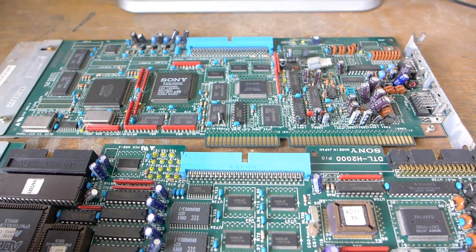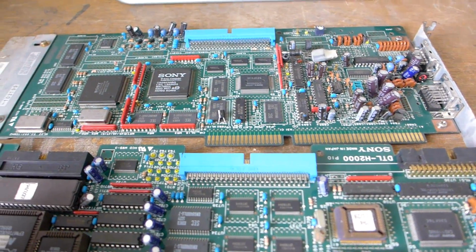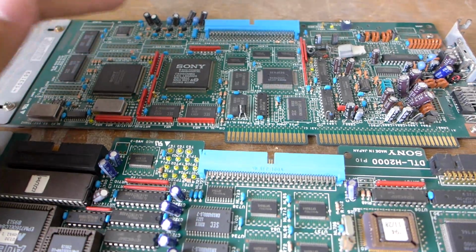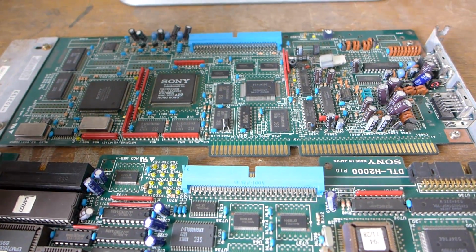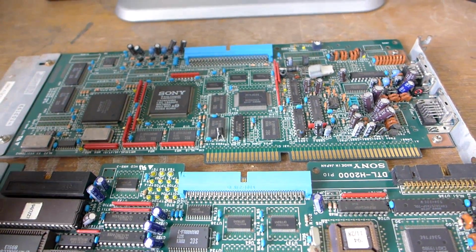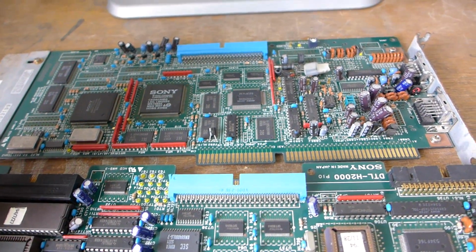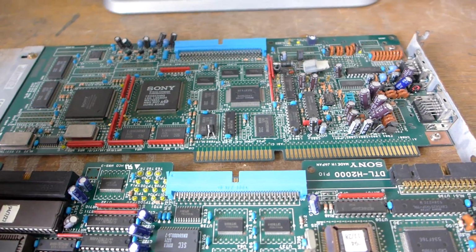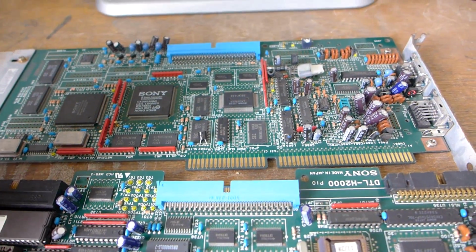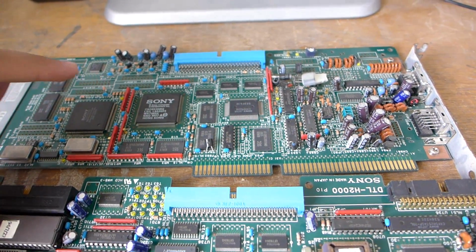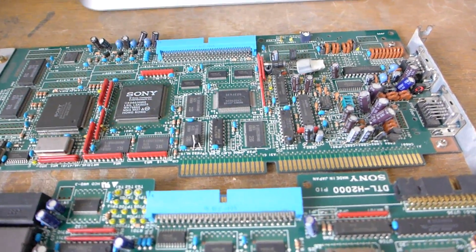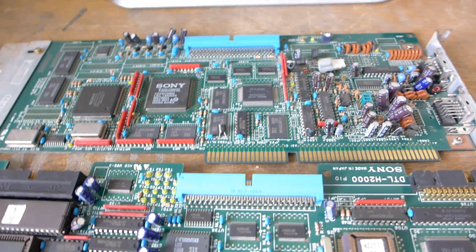And also there are two versions of the CPU board. The earliest one has a ceramic heatsink on the CPU, which resembles the very early Japanese launch units, which also had a ceramic heatsink on the CPU. The difference with that, as opposed to this revision of the DTL-H2000, is that the one with the ceramic heatsink has a bug where around 10 minutes of operation, there will be an I/O error.